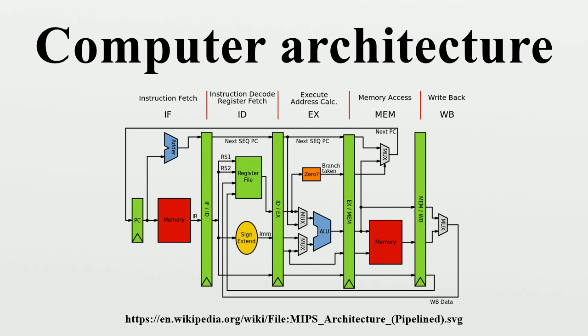Historic computers had IPC counts as low as 0.1. Simple modern processors easily reach near 1. Superscalar processors may reach 3 to 5 by executing several instructions per clock cycle. Multi-core and vector processing CPUs can multiply this further by acting on a lot of data per instruction, or by having several CPUs executing in parallel.